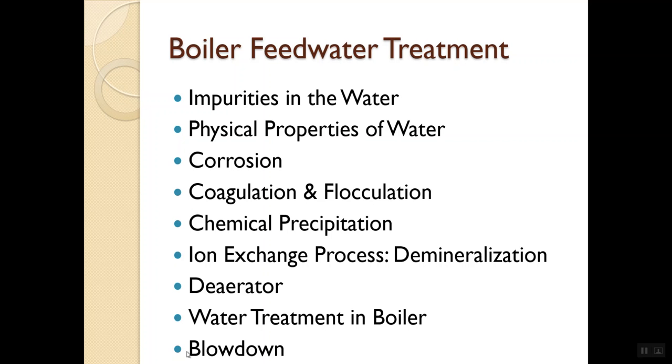So what we do is we take a stream of that water from the bottom of the boiler, and we open up a valve and we dump it down to the sewer system to get rid of it. As we get rid of that little bit of water, it carries with it any solids that may have got carried into the water or brought into the system from either outside sources or from the pipes themselves. As we have bits of corrosion in the pipes, that'll go out down the blowdown.